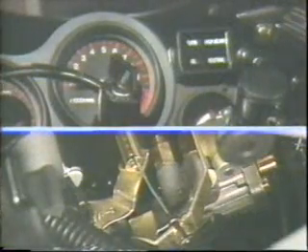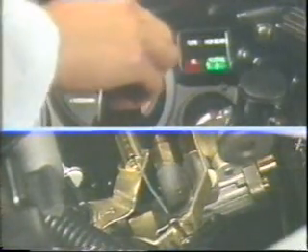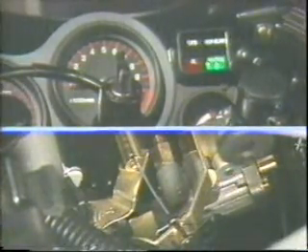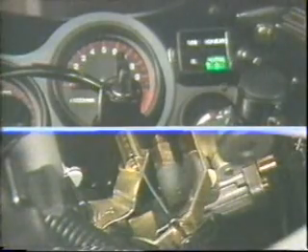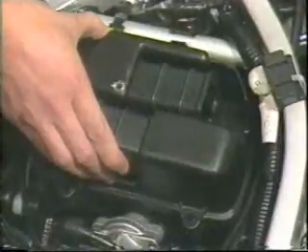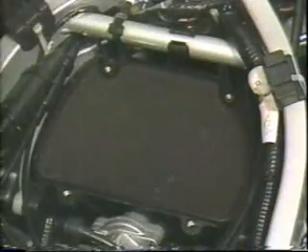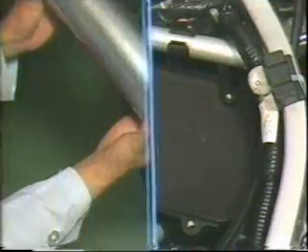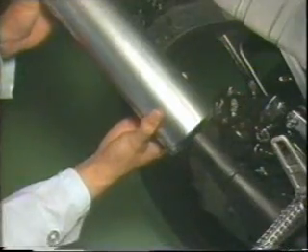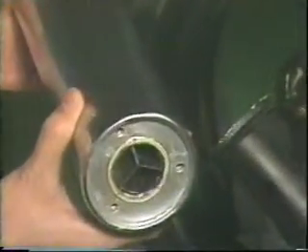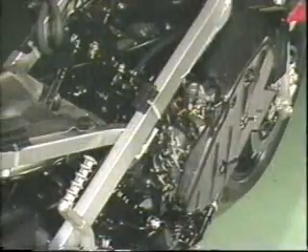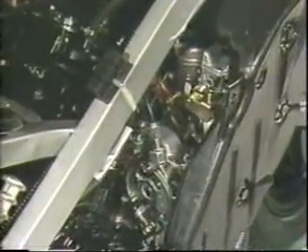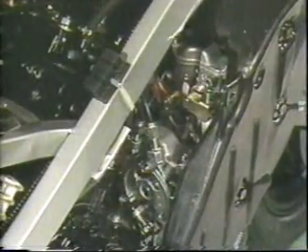The next test concerns the YPVS. Turn on the main switch and see if the YPVS is fully open. At this position, see if the oil pump is half open. If there is no trouble at this test point, you can check the intake and exhaust systems. When you check the intake system, look especially for any dust in the air cleaner. Then look for any excessive carbon deposits in the silencer or the muffler of the exhaust system. If nothing unusual is found in these visual inspections, the next part to check is each carburetor itself.